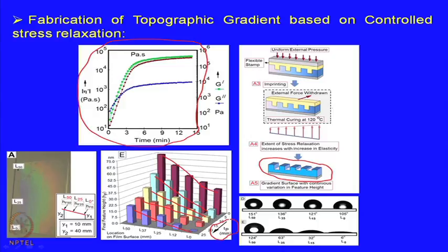You can also take different configurations of the spacer heights and can further control the steepness of the gradient. With appropriate stamps with high aspect ratio, it becomes possible this way to have the topographic gradient transferred to wettability gradients as well, and it is possible to achieve wettability gradients within the hydrophobic regime, for example, what you see here, or a gradient which ranges all the way from the hydrophilic to reasonably hydrophobic extent.